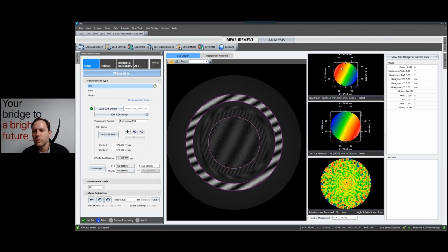And that's because between this raw input, we then move to the middle plot here with the surface deviation. Going from the raw input to the surface deviation is where we laterally rescale or remap the data. Now at this point, the data has been dimensioned properly so that if we have a high point over here and we're going back again to our, say, sub-aperture polishing tool, we know that is correctly scaled so that that polishing equipment then can polish the correct location. Obviously, if you had said that was at 57 millimeters, you would make your part incorrectly.